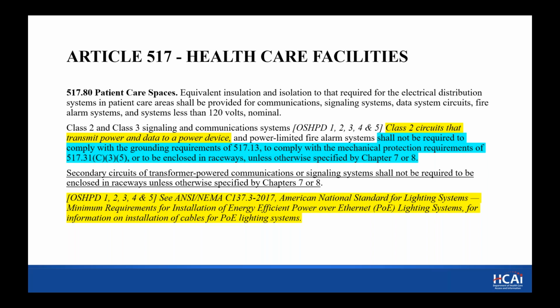The only place where you can combine normal and emergency would be in a transfer switch, or in a light fixture. So yes, that would need to be separate. Wonderful. Thank you. Two more questions and then we will be done. And thank you so much.